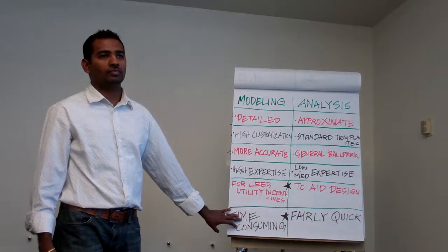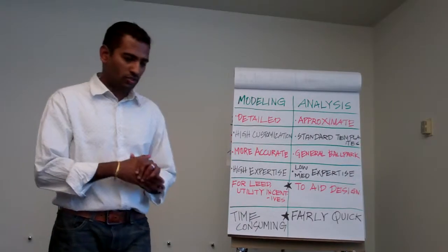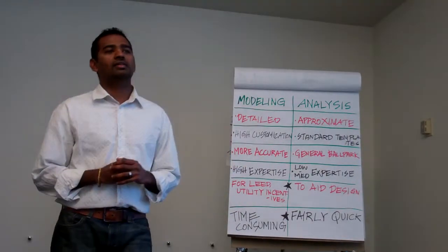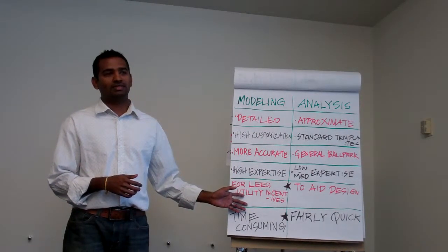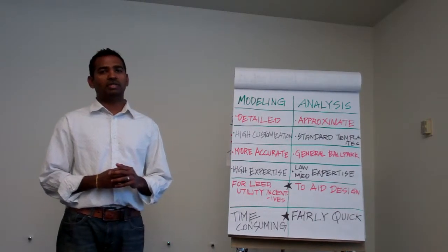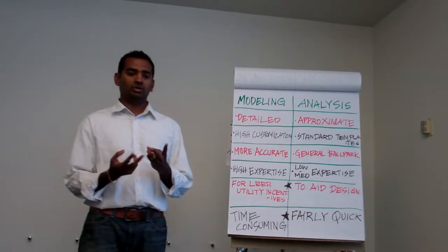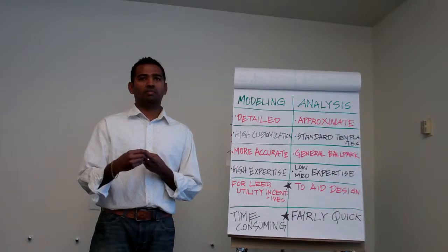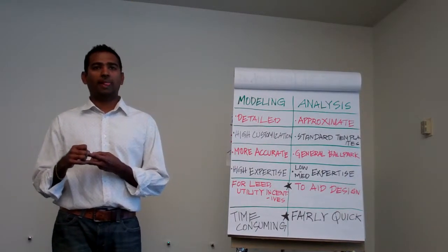Grim, can you qualify that? What you just said about LEED, because you don't have to do modeling on all LEED projects, right? That is true. You restrict on the number of points you get. But yes, just because you have a LEED project doesn't mean you have to model. That's true. But typically, most projects do go after LEED energy optimization points more than just the minimal points. Because LEED allows you to not do an energy model and just go by with meeting the standard codes to prove that your building is energy efficient.